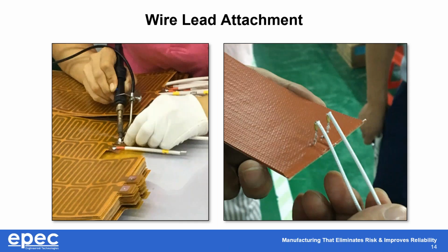Keep in mind, our heaters aren't just a heating element. We can add discrete components like thermistors, thermocouples, and other temperature sense devices. If that's part of the design, there may be more than just 2 wires needed for the heater to operate, with these 2 being for power and additional sets of wires being necessary to monitor the thermistors and other temp sense items.